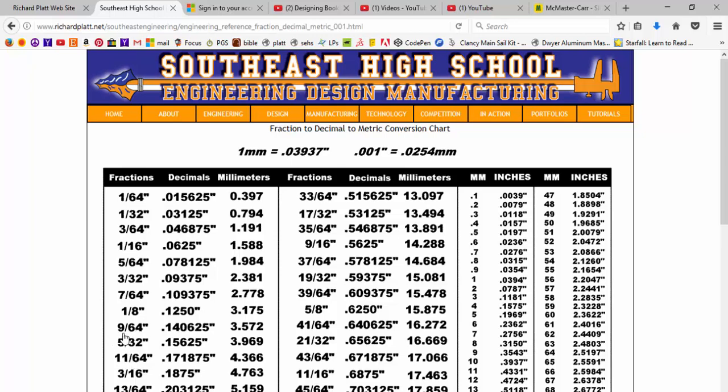I use 3/16 drill bits all the time. So that's one I'll commonly have in stock or in my toolkit, or I'll go buy a lot of 3/16 because I use those typically with an 1/8" screw. So it gives me a little bit of play. Also gives me room to put some glue down in the hole if I want to glue that, which in this case I would. So we're going to put a 3/16 diameter hole.